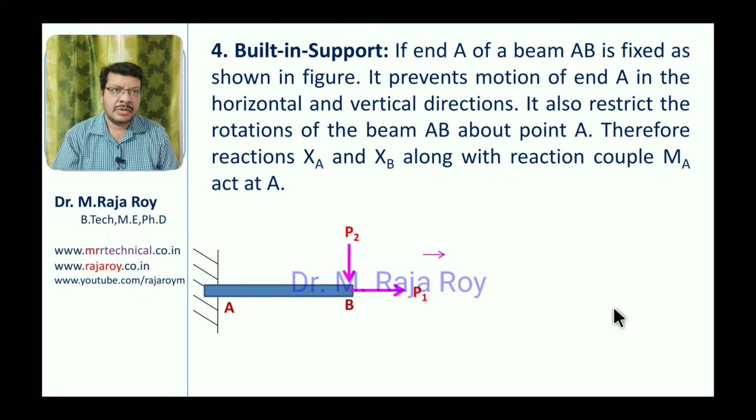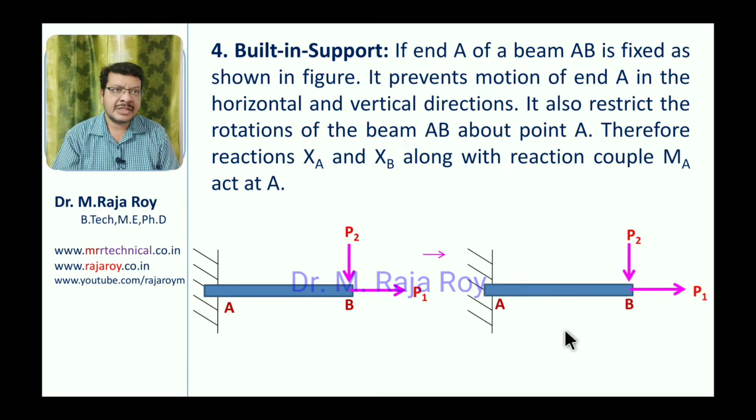So here you will get reactions like this. Three reactions you will get. If you replace this support, you will get three reactions: Xa, Ya and a moment. In this way, you have to replace the built-in support with three reactions.